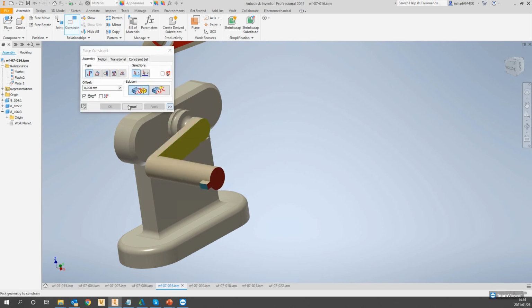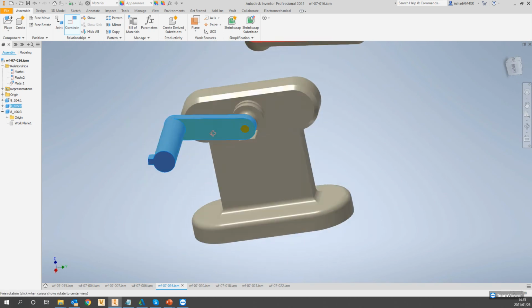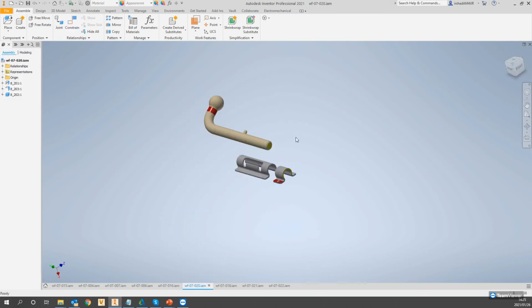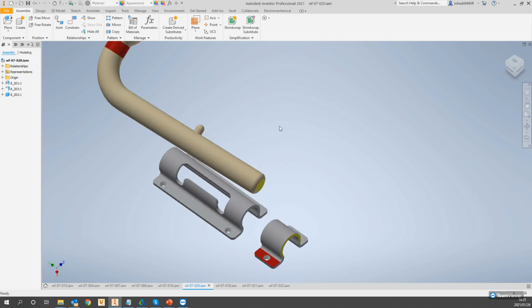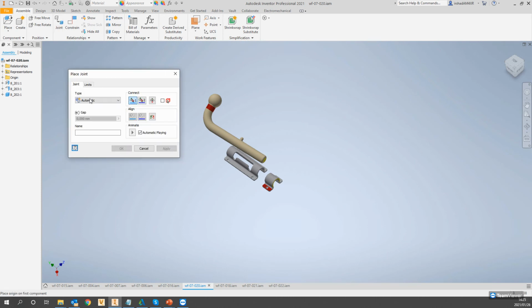Right. So the problem is, like I was saying, that is now rigidly fixed. You'll see here, it allows you to rotate that. However, if we wanted to do some joints, let us discuss a new example using joints. So what I can do with joints is, instead of removing all those degrees of freedom, I can have either a rotational, slider, or cylindrical joint. So let's just take a look at the difference between all the types of joint.